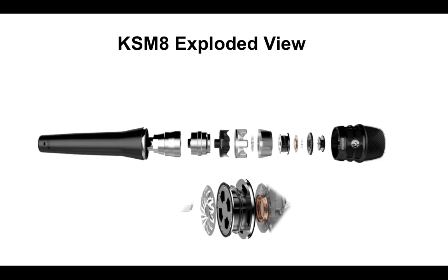Completely new engine, as you will, quote unquote. There's a diaphragm with the coil. We use a new aerospace pole piece material called soft mag. It's a very lightweight, very ferrous metal that they use in the aerospace industry. And most of the time, the pole piece that we talk about, which directs that magnetic field, is just made out of steel. We had to hit a certain weight on the cartridge for durability, and we had to borrow this from the aerospace industry. And it gives us actually more saturation of the magnetic circuit, and then that second diaphragm is there passively to control that proximity effect, and we'll talk about how that is in the next slide.